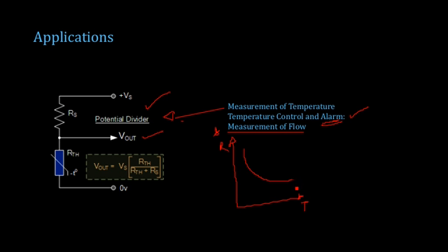The reason is that the heat dissipation is balancing with the heat that is provided into this resistor, so that once the flow of fluid is able to remove the heat from the thermistor efficiently in a steady state manner, the temperature will not increase and the resistance remains the same.